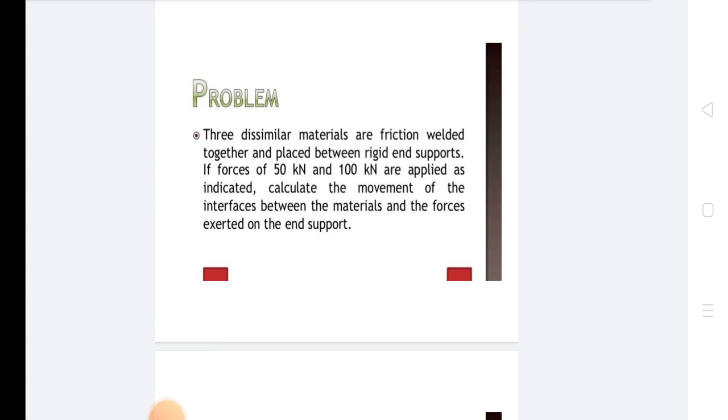So these steps are very important for solving the FEM problem. I repeat these steps again: discretize the given model, selection of displacement model, find the element stiffness matrix, assemble the global stiffness matrix, apply boundary conditions, determine unknown parameters.